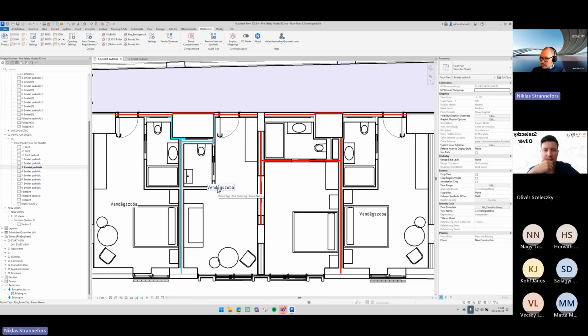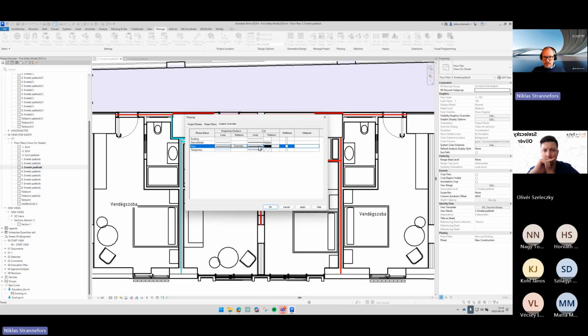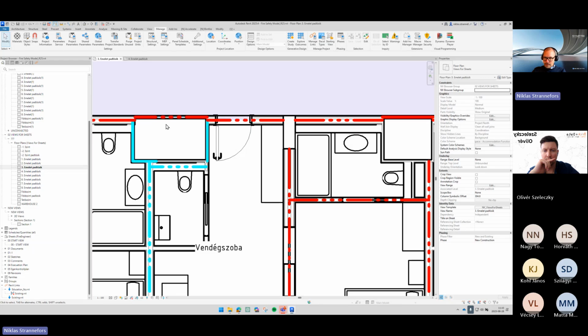It can look kind of chopped up. What we're doing is actually placing a requirement on each and every component. I know Janos, Laura and Mercedes, you have a dashed line. We have a solid line because we had the override. We can remove that as well. I will remove it here on phases. Override the dash here, the solid line. We just clear the override on everything and go back, so we have exactly the same. But you can see that it's chopped up like this, and that is because we are actually adding a requirement and mimicking every wall as the architect has drawn it.